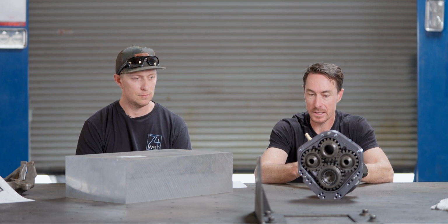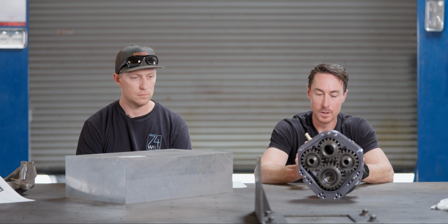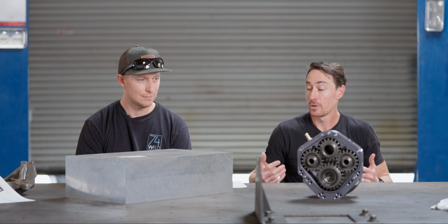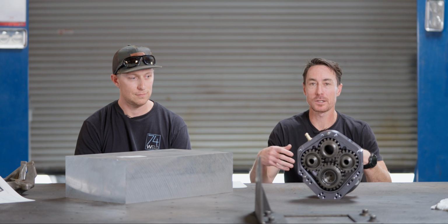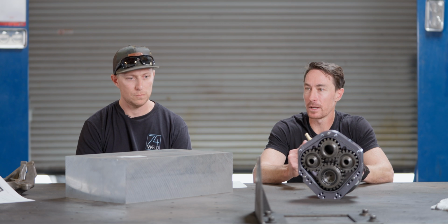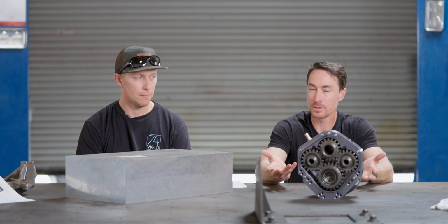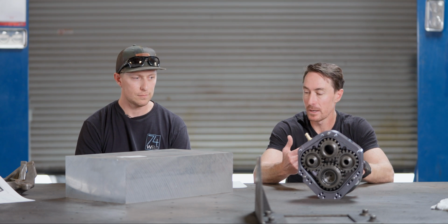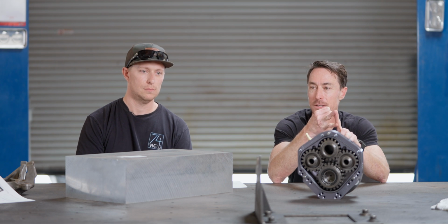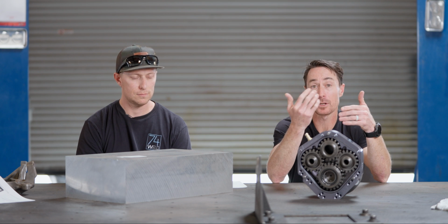And this lesson was really ingrained in my head years ago. So if you want the best axle shafts possible, you make them out of 300M, and then there's a whole tempering process to heat treat and then temper it back down. 300M is known as kind of the industry standard for axle shafts in high torque applications. You can heat treat it to a higher Rockwell hardness. It has better toughness. It has better tensile and yield than the lower grades of 4340.